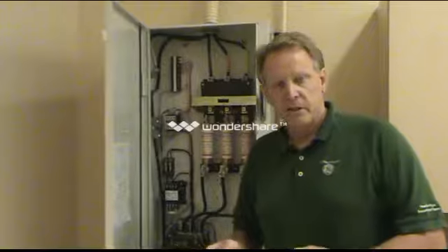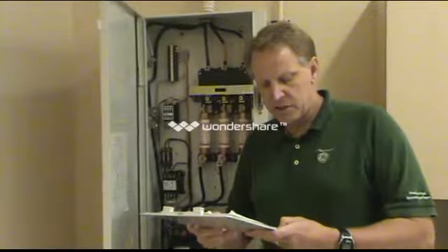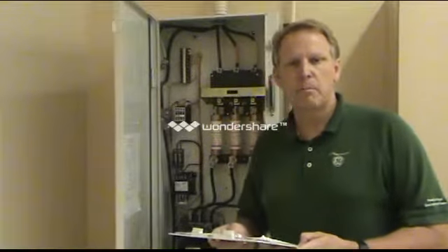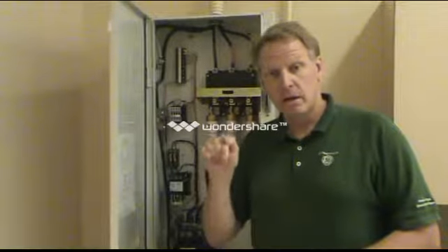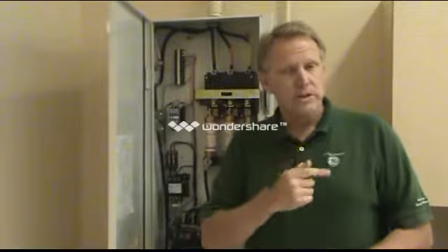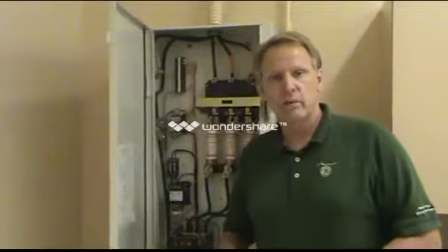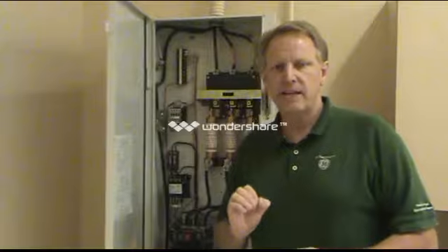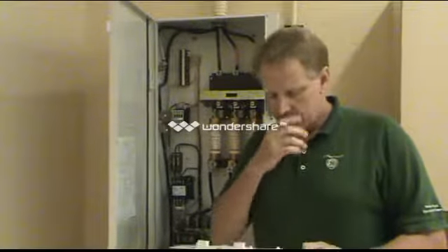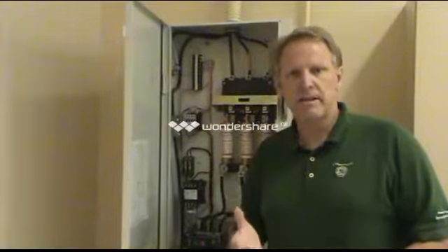All right, step 3, is there an e-stop or emergency shutdown device readily accessible to the operator? Typically all that requires is the e-stop button on the console or the gantries or the tables. So if those are within reach, then you can check yes to this. It does not necessarily pertain to a shunt trip device. There's been a lot of questions in the past about that.